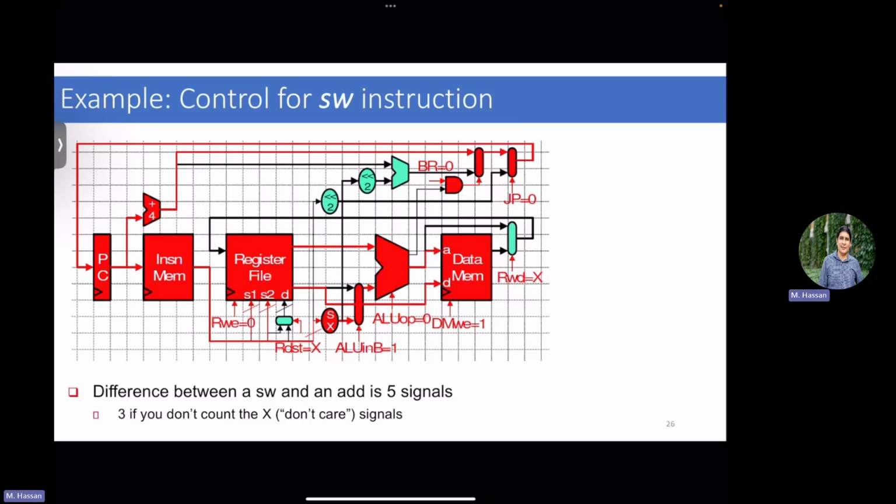So you need to read an offset, and this offset simply comes from, so just remember the storing thing for you. There is source 1 that you add to an immediate value. You take the address and then simply go to the memory and you write to the memory or destination, right? That's really what you do. This is address, this is data, and this is mem. So you need to enable the write enable for the mem.